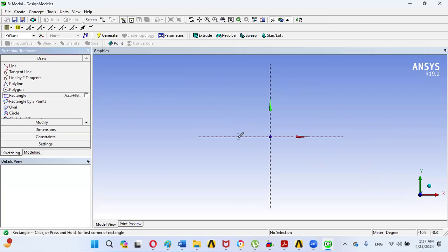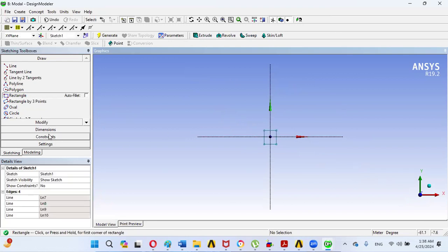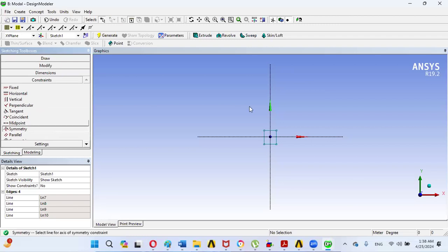And then here we can, for example, create a simple volume, and here we can make a symmetry axis and click on this point and click on this point, so that, and after that we will be creating a new symmetry axis, this horizontal axis, and then click at this location and at this location, so that it has been made symmetric.